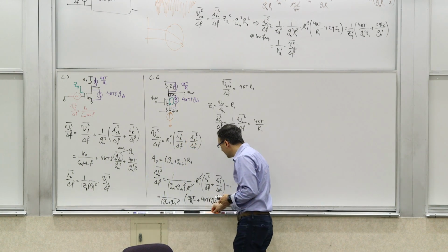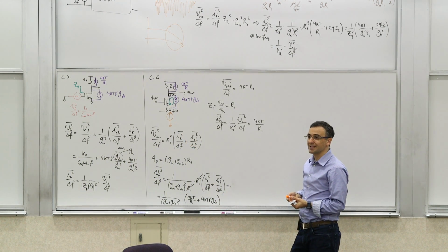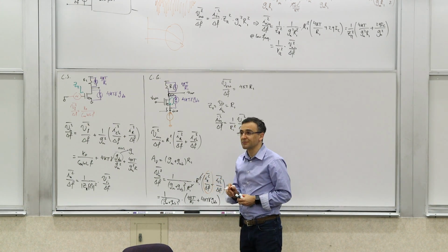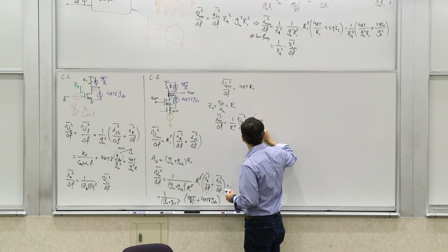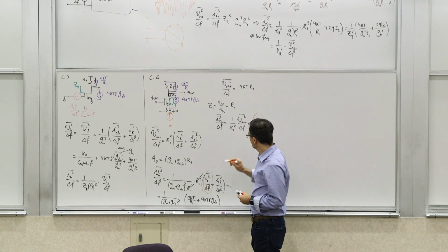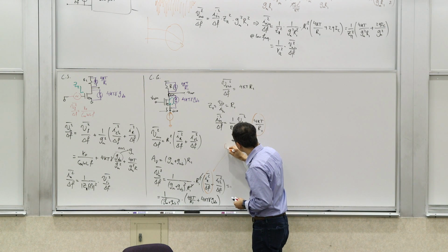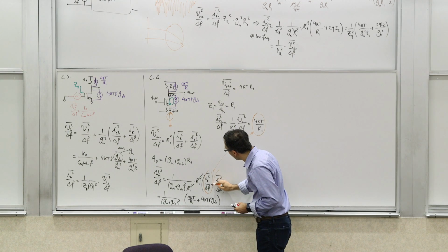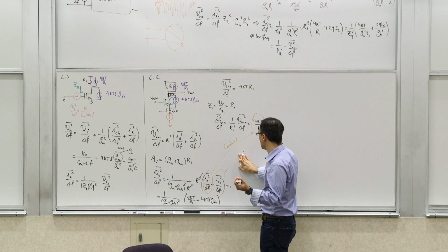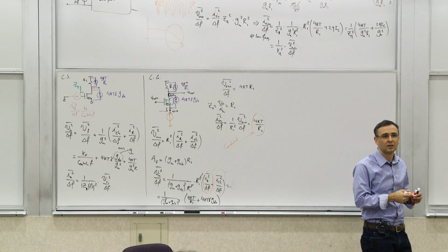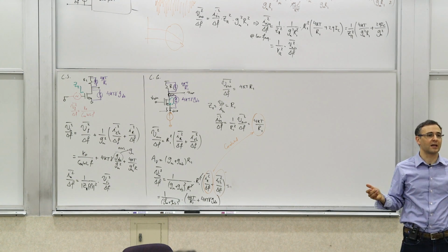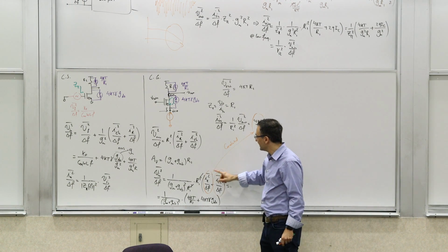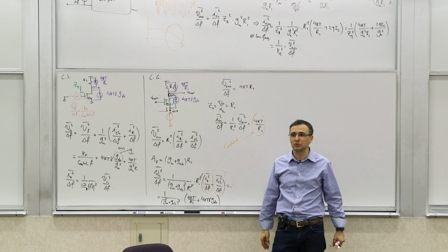So which parts are correlated? Well, the parts that are produced by the same physical phenomenon, right? In this example, this is produced by the resistor, and this noise is produced by the resistor, the load resistor. So these parts are correlated. But there's this other part that's not present there and therefore is not correlated. So this is an example of two partially correlated noise sources. So these parts add in amplitude, and this part adds to them in power.